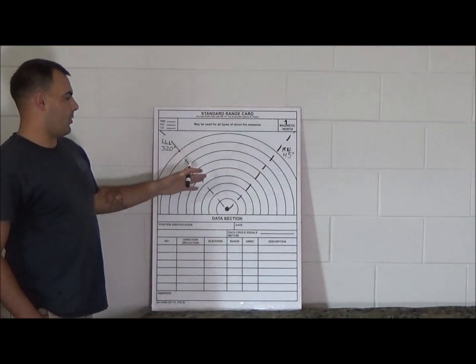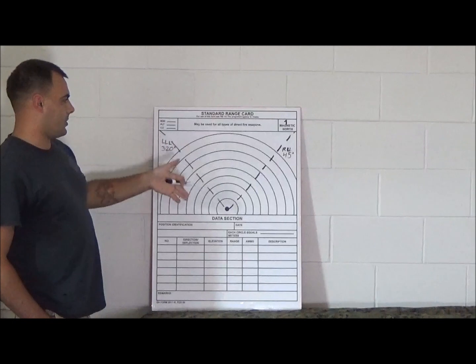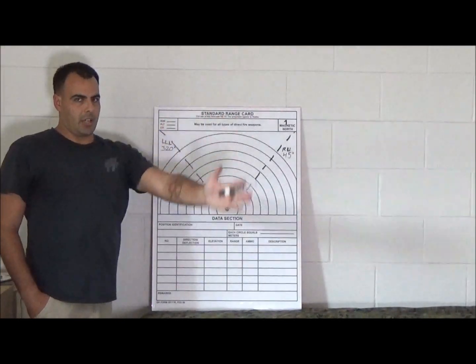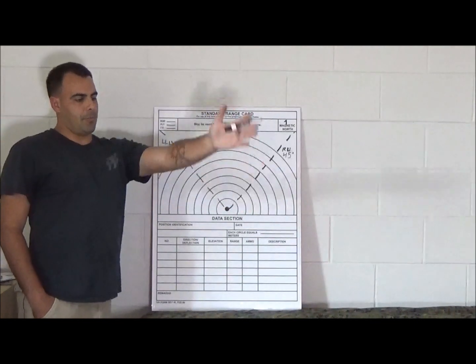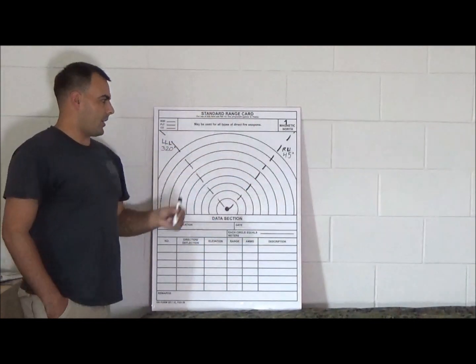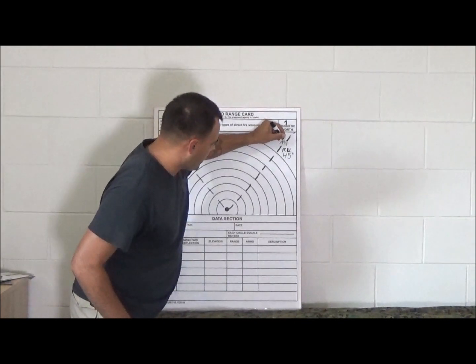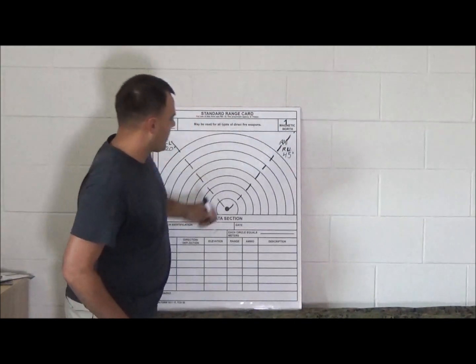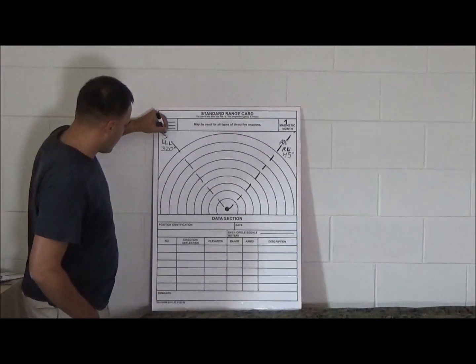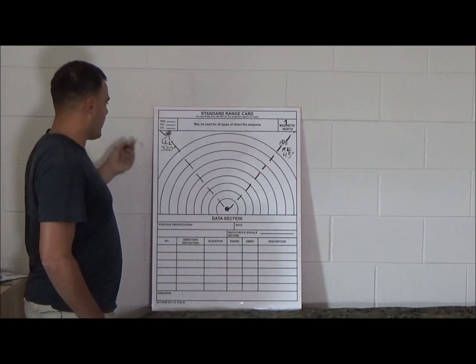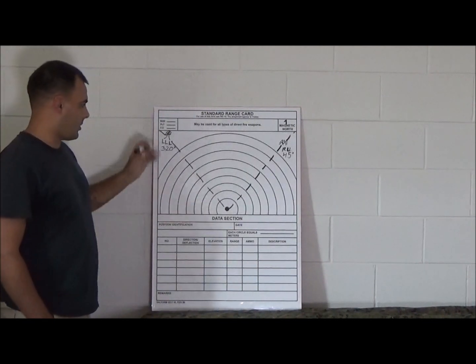And another method we can use, if we don't have a compass to get degrees and directions, is if there's something I can see along that line, either on the horizon or something in between, that I can draw on there. So let's say on this side I have a little rocky outcropping here. And on this side I have one lone tree by itself that pretty much anyone can come out and see and know that, okay, that one tree is the other lateral limit.